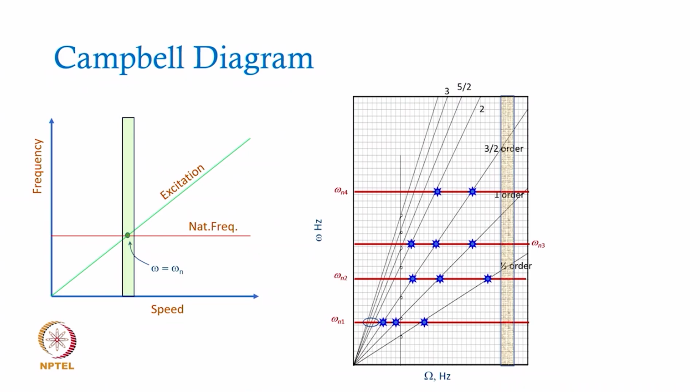For example, we discussed the blades, the steam turbine blades or gas turbine blades when they are rotating, and if we plot this Campbell diagram bringing in also the natural frequencies of the blades into the picture. Now, for blades, the natural frequency line will not be horizontal. So, in case of blades, it is quite common to have the natural frequency not be a horizontal line, but a curve tilting upwards, and there are reasons for this, which you think about yourself.